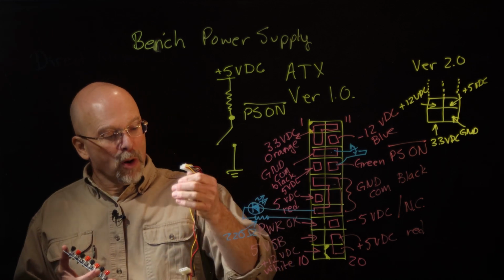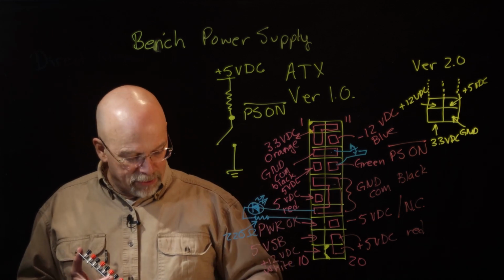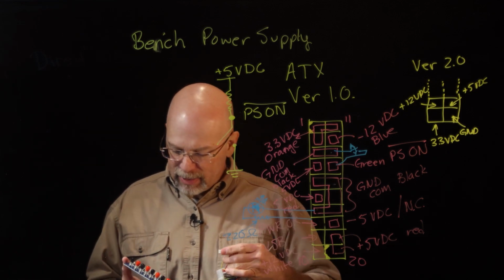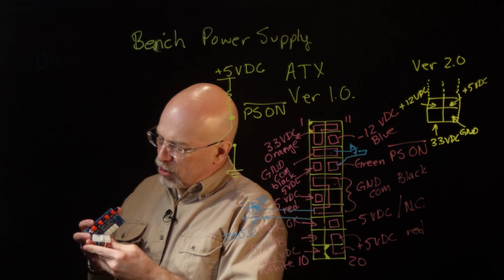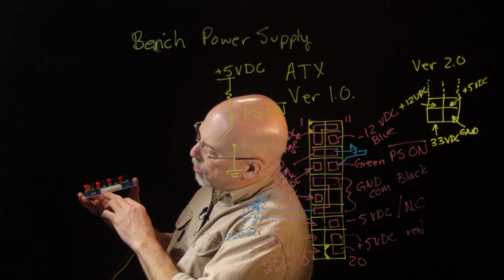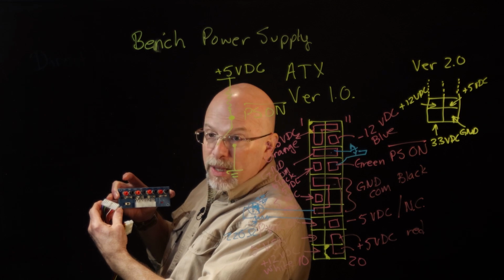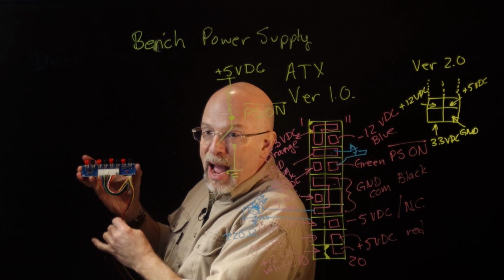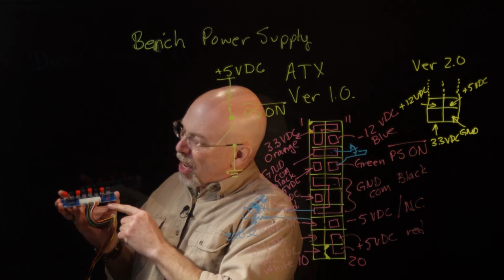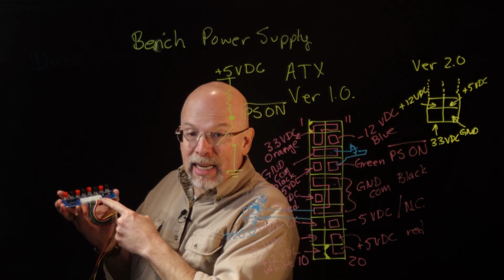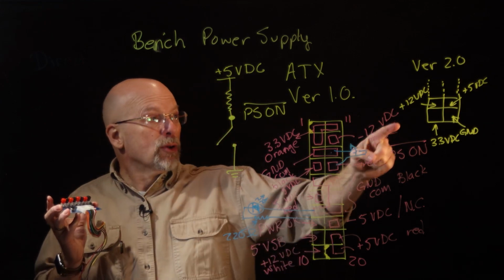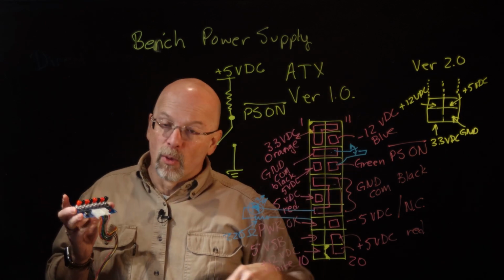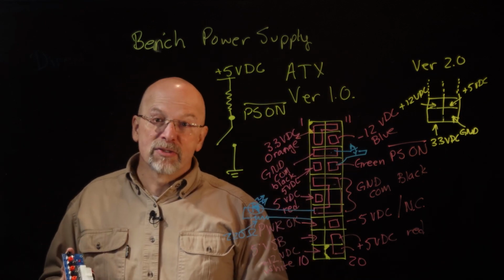Now, as I said before, what I've got for this little power supply here is just the 20-pin ATX connector. And so all I have to do is just simply know that this is pin 1 and this is pin 1 on this connector, line them up, it will plug in just fine, power directly from the power supply, and leave those 4 pins disconnected or just floating. But remember, those 4 pins just provide voltages that are already provided on the version 1 form of the ATX power supply. So there you go.